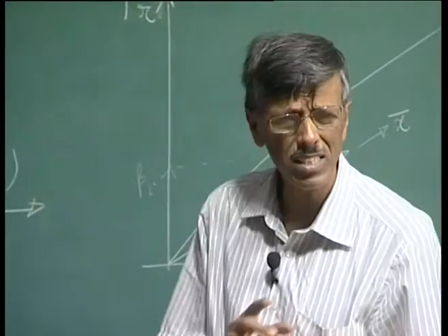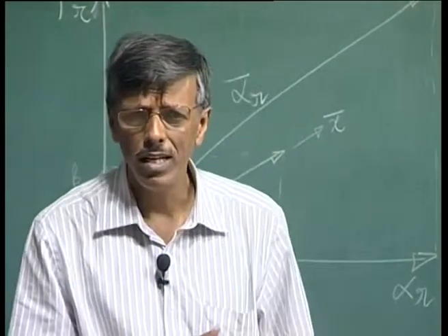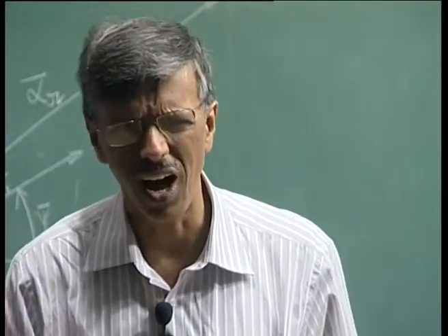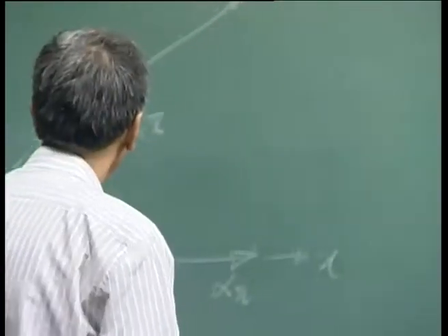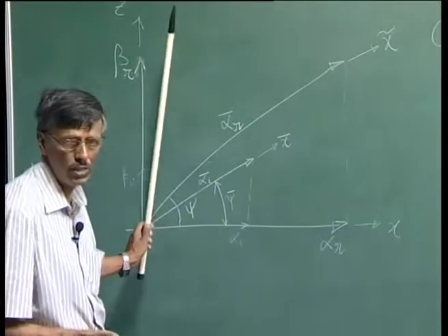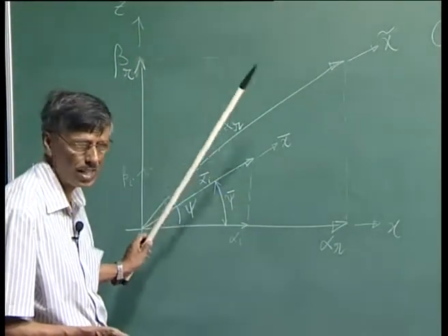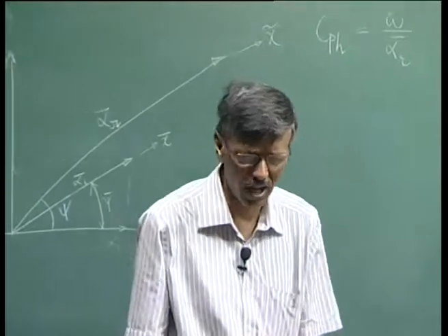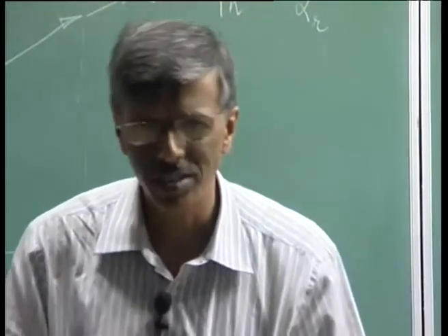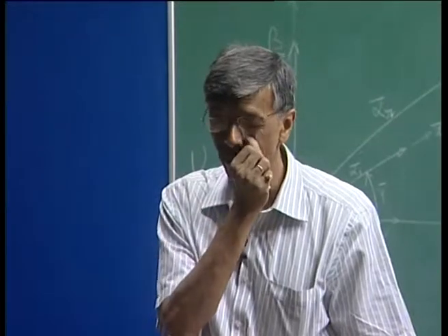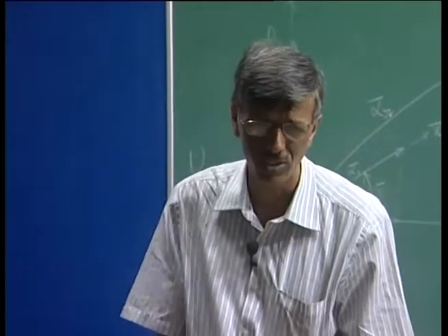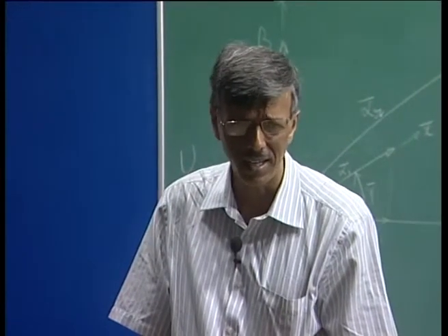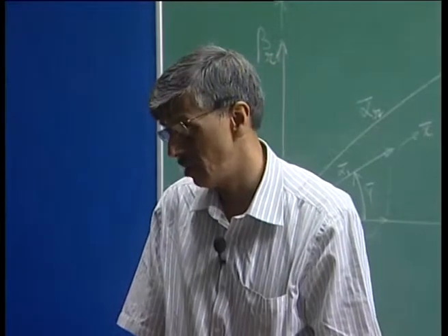And please do understand that these complications that we are getting are because we are talking about a 3-dimensional disturbance field. So, alpha and beta make all these things, but if I look at a 2D disturbance field, then everything goes in the x direction. So, all these complications are with respect to a 3-dimensional disturbance field. It is not imaginary or illusory to consider that, because if, let us say, we are designing an aircraft wing, we do very often see that.